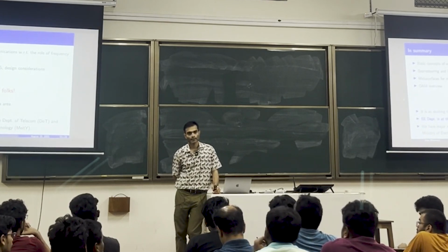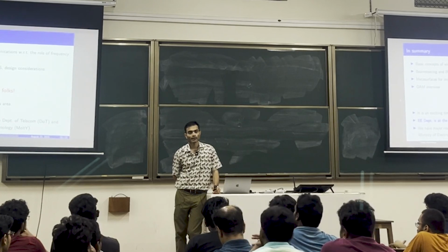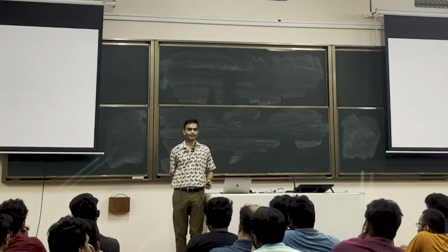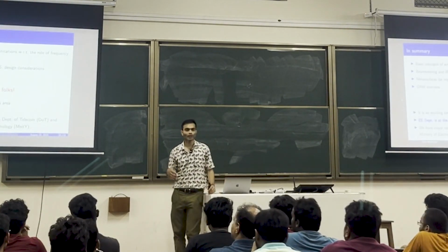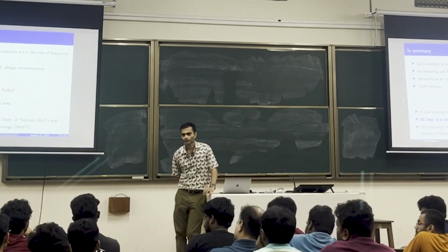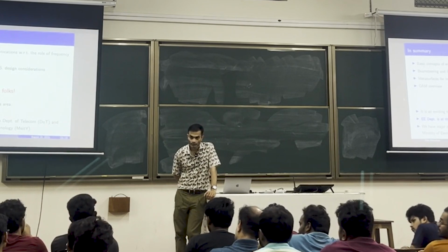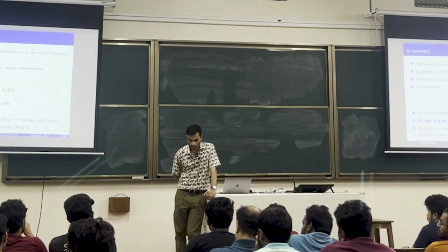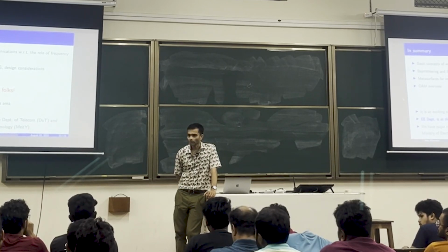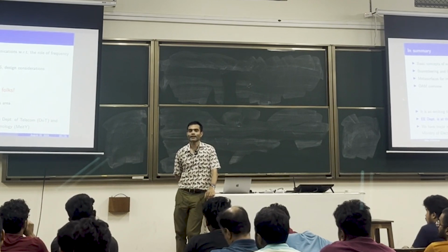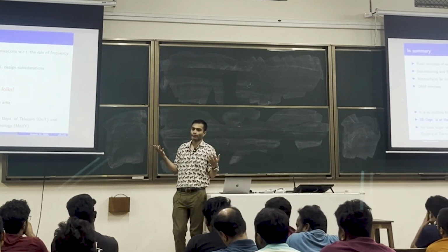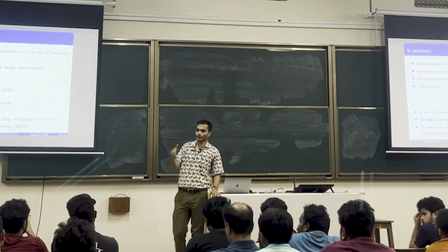And the power, what is the minimum surface you require for this? That's a calculation that you have to do. It's called link budget analysis. How much power is required, you can do that calculation. Not a very difficult calculation. This IRS technology is dynamic and adaptive because the users could be moving in this space. Can the adaptive be used for high mobility applications? You need it when you are going out of line of sight. If I am in line of sight, then I don't need it. But if I am going in and out of line of sight, then yes, I need this.